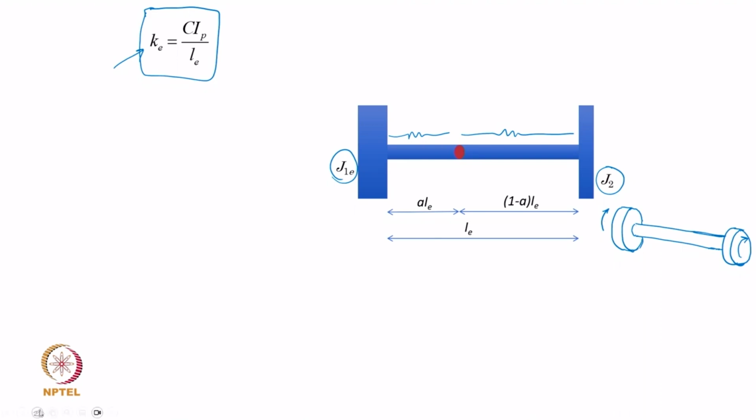So, in this particular case, the motion now is going to be this mass moving in the counterclockwise sense and this one in the clockwise sense. So, there is now going to be a twist and strain in the shaft. So, this shaft is going to be under torsional strain, shear strain, and then what will happen is that this disc is going to move counterclockwise when this is going to move clockwise, and after some time they will flip their direction. So, they will keep on oscillating like this.